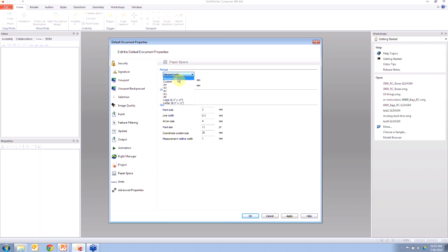The document's constantly looking at the viewport ratio of each view, and you can control that per view, which is really nice compared to setting this to legal or letter, which forces every single view to be that size. This gives you more variation and allows you to control the document a lot better. So it's currently what I recommend.